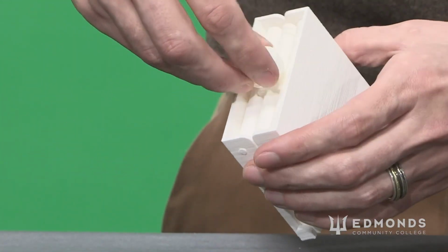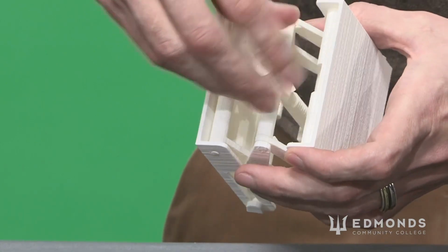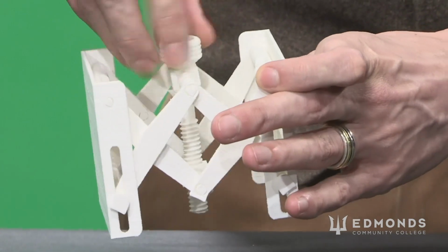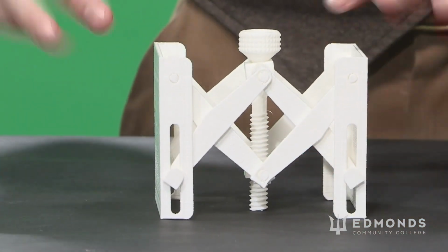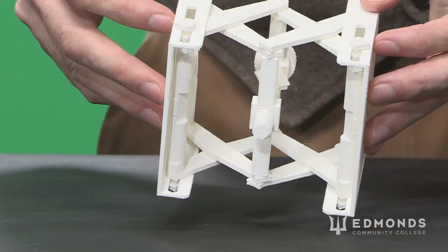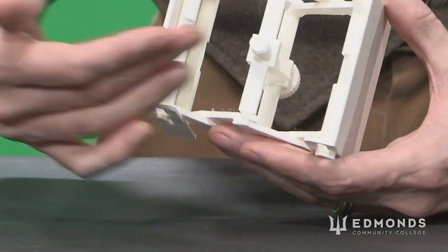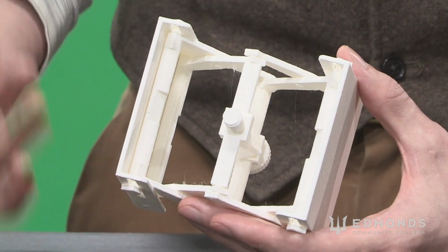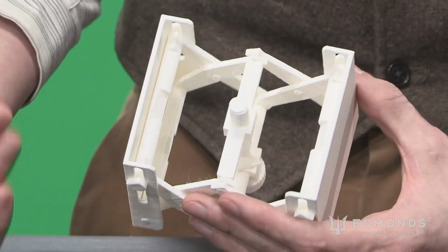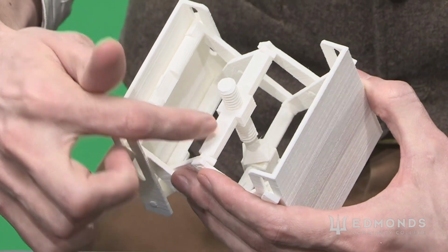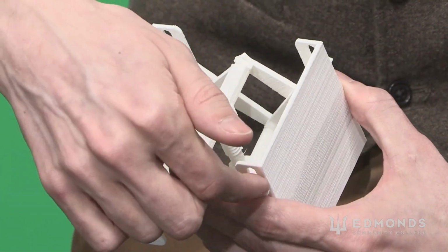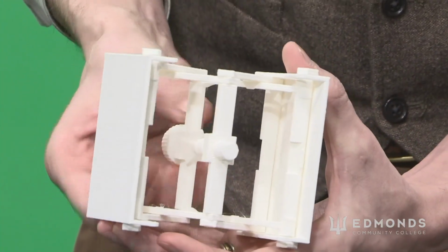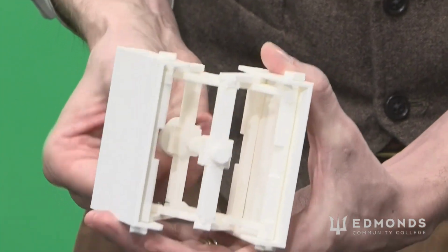However, once we look inside, the AM technician will discover that this needs to be printed upwards in this direction while closed in order to be produced successfully, because all of these moving parts need to be printed without touching each other and therefore without relying on each other for support. So all of these components, this face, this face, this face, and this face, and these two faces, will all touch the ground when printed in that orientation.